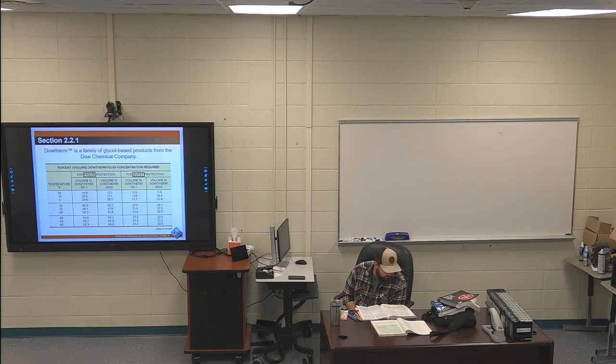222, preparing a system for chemical addition. The first sentence is an online test question. When preparing to add winterization chemicals to a system, the most important step is to first ensure the system is clean. Making sure the system's clean, step number 1. Skip 2 sentences all the way in the bottom left of 22. I got another sentence highlighted. Chloride ions found in acid cleaning solutions must be cleaned out.